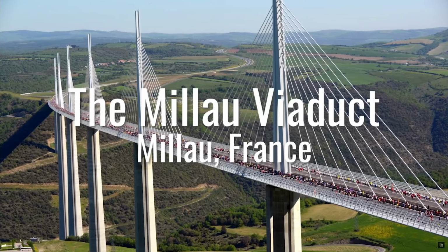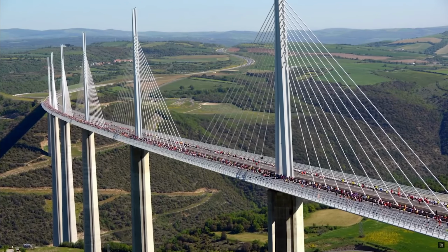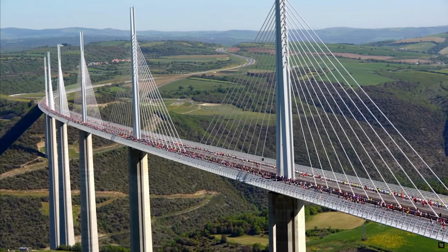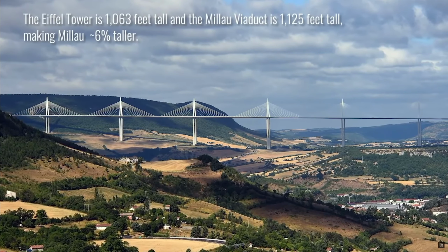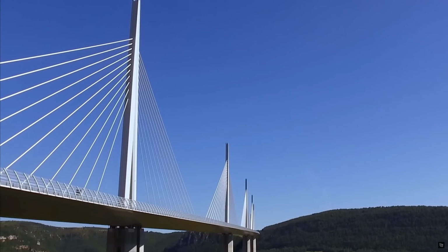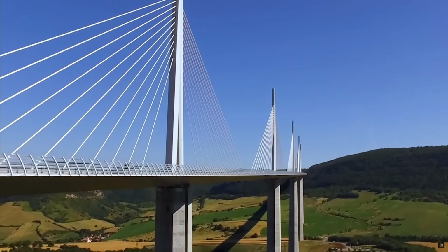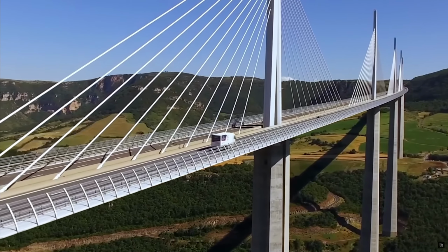Yes, so the Millau Viaduct is actually the tallest bridge in the world, being that each of its piers is about the height of the Eiffel Tower itself. And from it, you have your cables that are keeping the deck in place, making it a very aesthetically appealing bridge, but also using the counterweights of both sides to be able to have a much longer span in between piers than you would with any other bridge type. It's only but so long you can design a plank or a girder.